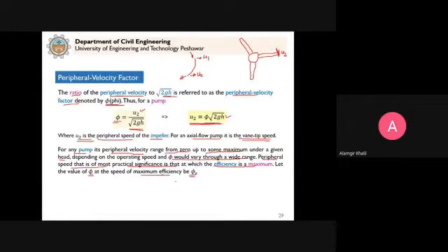And then from here, what can we write down? We can write down U2 is equal to 2 pi r NE by 60, where NE is in revolutions per minute. This is the tangential velocity, in the linear direction, as we discussed in the previous chapter, momentum and forces in fluid flow. So this U is equal to R into omega.